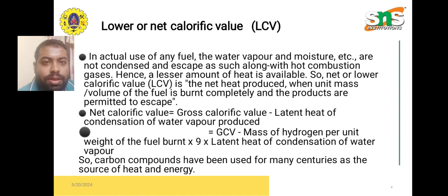Then about LCV, which is also known as lower or net calorific value. In actual use of any fuel, the water vapor and moisture etc. are not condensed and escape as such along with hot combustion gases. Hence, a lesser amount of heat is available. So, the net or lower calorific value LCV is the net heat produced when unit mass or volume of the fuel is burnt completely and the products are permitted to escape. Net calorific value is equal to gross calorific value minus latent heat of condensation of water vapor produced, which is equal to GCV minus mass of hydrogen per unit weight of the fuel burnt into 9 into latent heat of condensation of water vapor.